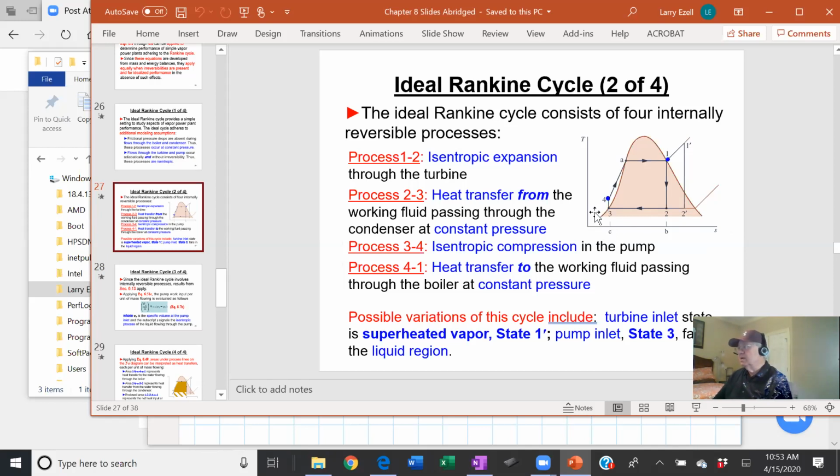It's hard to say. And this is constant entropy. This area can give you some problems calculating because it's hard to look up these values in the table. Now the problem I gave you said to use the compressed liquid tables, and those values you could look up in the table we have, but the table's not very good.